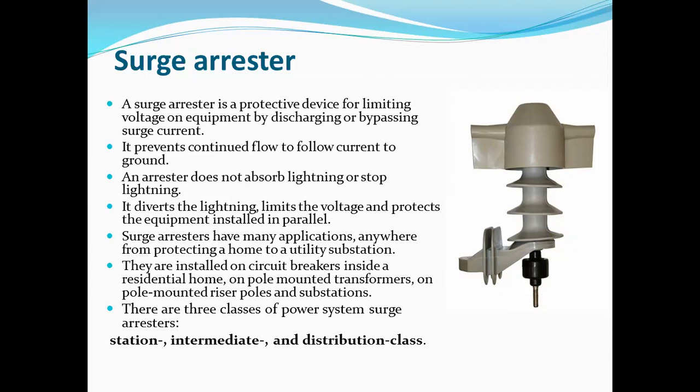So there is one more equipment, that is the lightning arrester. It is not actually absorbing or stopping the lightning. Okay, they are just bypassing or discharging that surge current. So it diverts the lightning, limits the voltage, and protects the equipment installed in parallel.